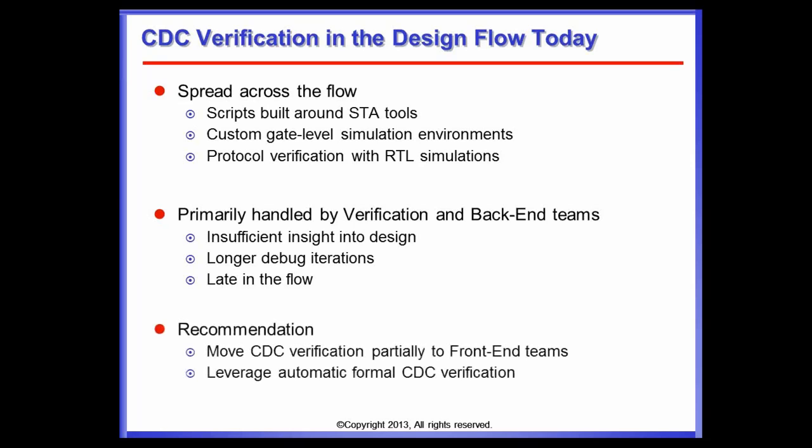So the recommendation, in general, is to use a dedicated CDC tool. That way you can move, or partially move, this kind of verification into the front-end teams, because the verification itself is automated with a dedicated CDC tool, not breaking the rule that the designer should not verify his own block using his own rules, right?